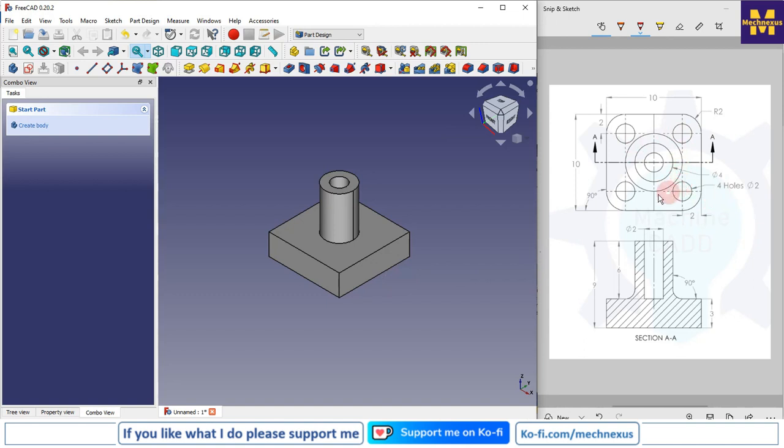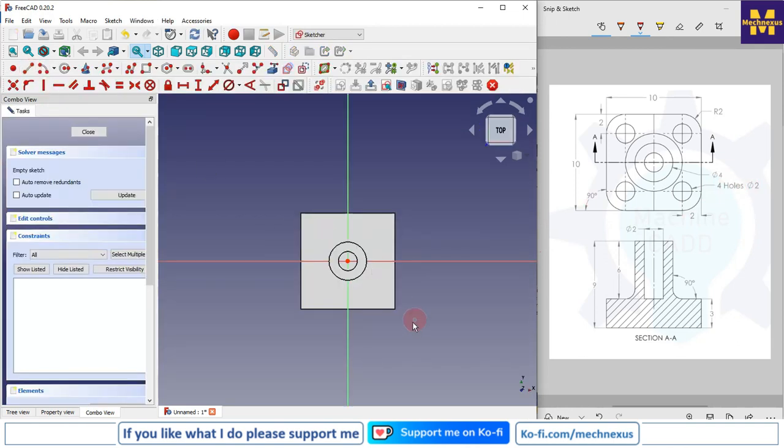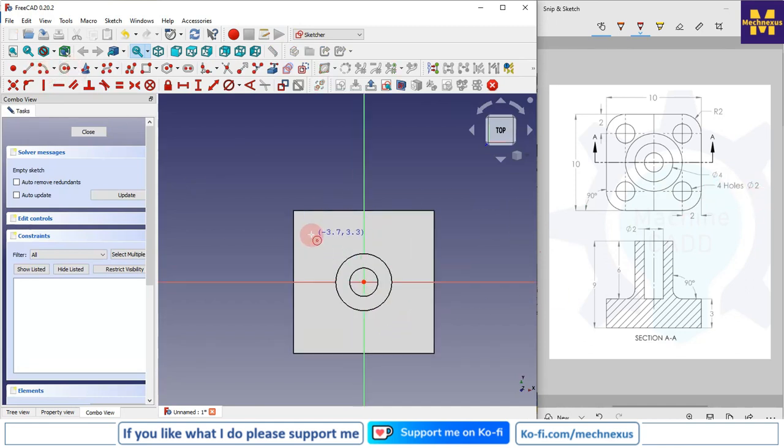Now we will give these 4 holes. As we can see, it is 4 holes of diameter 2. I will select this face and create a sketch. It is a blind hole, so we can make it through the cut feature. I will select 2 circles here and 2 here, and now we will see the position is 2 mm horizontal and 2 mm vertical.